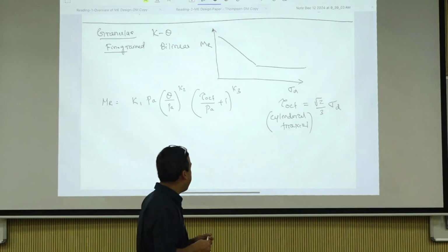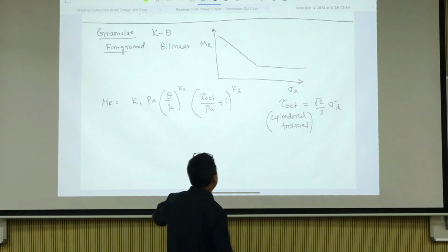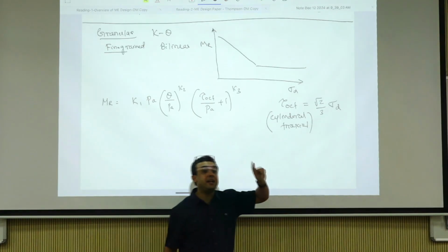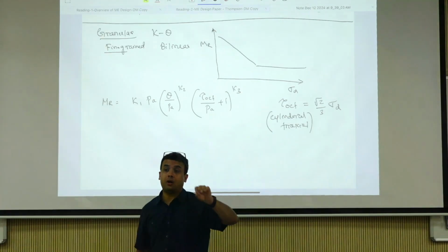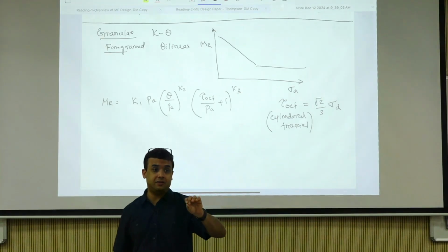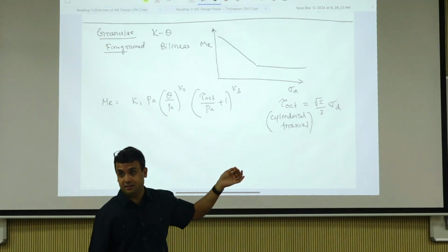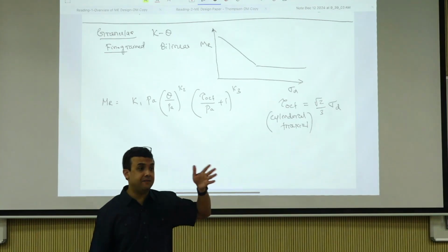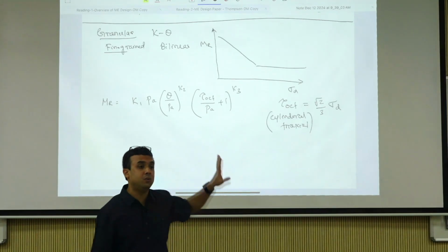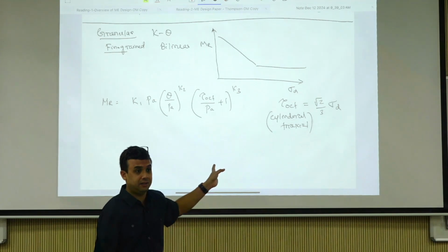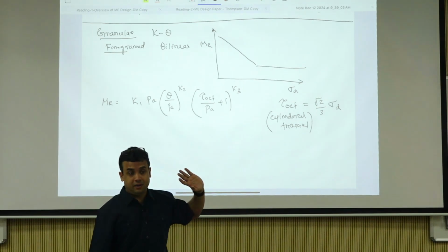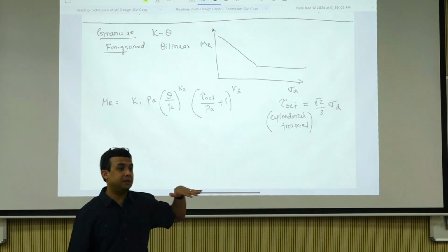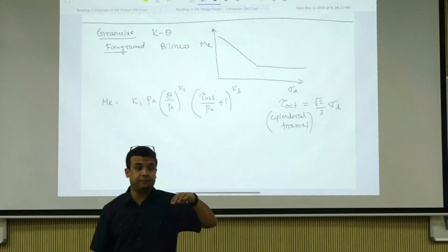So we are actually not capturing what is known as level 1 inputs for subgrade soils and aggregates in MEPDG. It's still level 2, because we are not doing true stress dependency in there, at least as of now. There are plans to make that improvement, but it's not there yet, right?